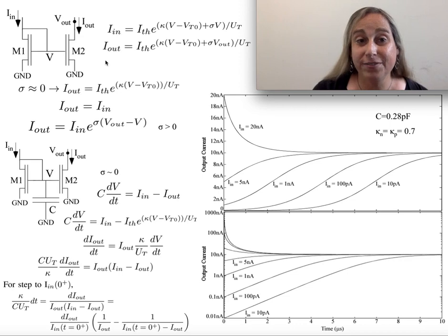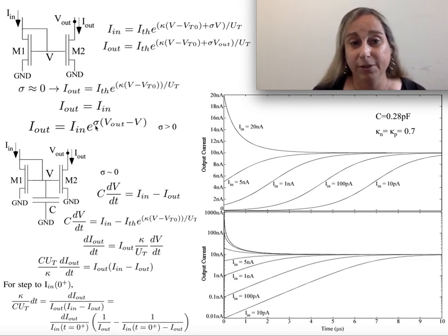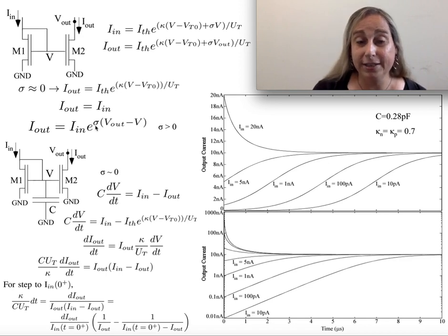Now there's a slight shift in there, because if you assume that sigma equals 0, well, then it solves a little bit easier. But again, here's what the transistor curves look like assuming sigma's there. Now, if sigma's 0, I out just becomes I in, and you're like, yay! Now, if sigma's not 0, this is going to change a little bit. And so that's something you would look at in terms of dynamics. And so you can see a little bit of a shift, and you're still going to see things like limitation of gain if you're using a current mirror to load into another transistor. On the other hand, it's going to be fairly good, and you can kind of work with these devices.